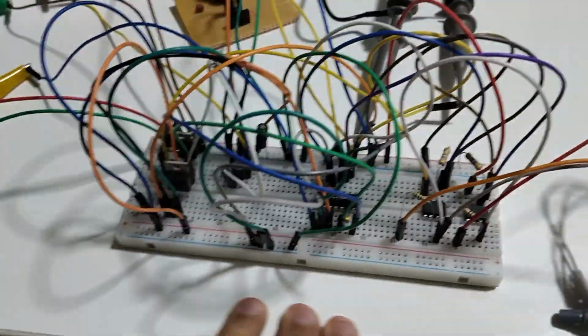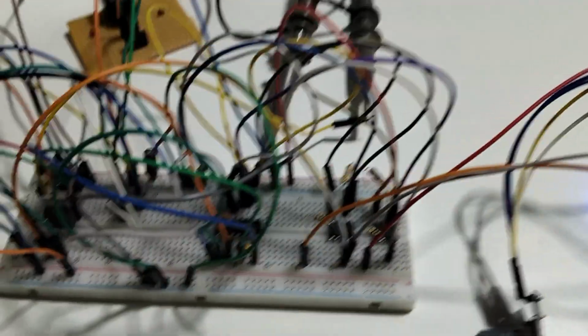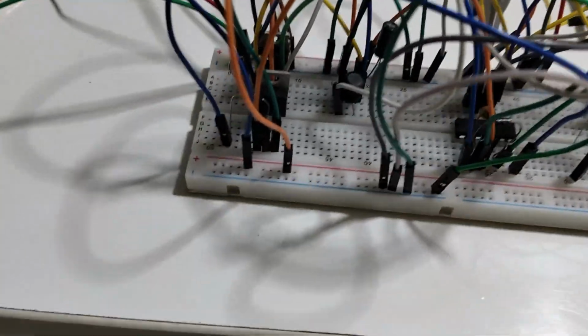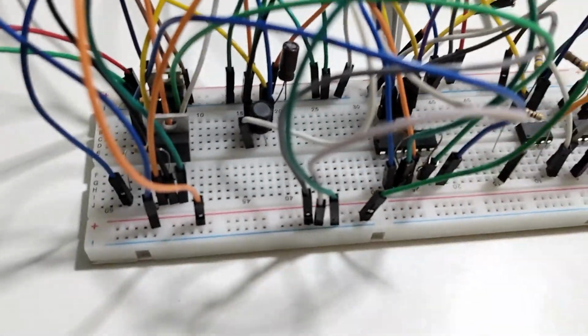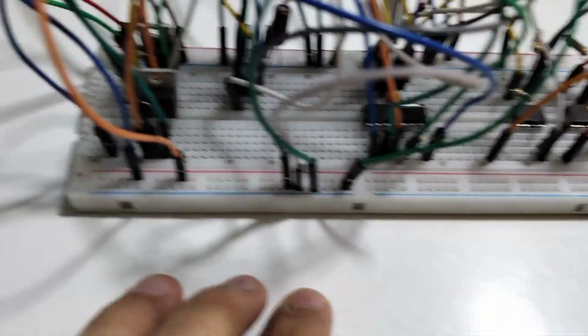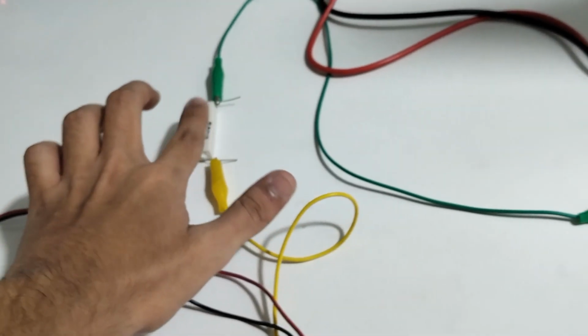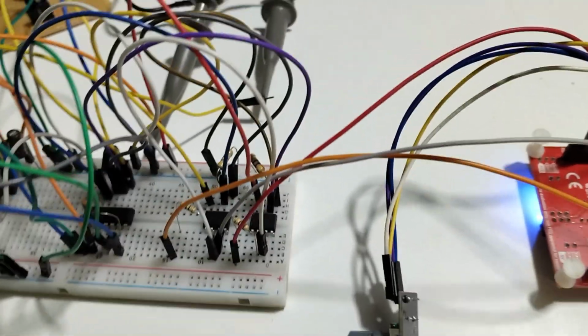And the learnings out of this is, of course, the half bridge needs dead time. That's a term that gets thrown around a lot in power electronics, especially any kind of power converter which uses a half bridge or full bridge. So this uses a half bridge, and later if you want to drive a motor or something from this, you can do that too. It's a buck converter. Here I used a resistive load, but you can go for a motor too, and see the motor speeding up and slowing down.